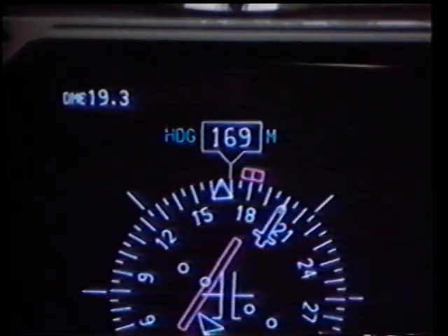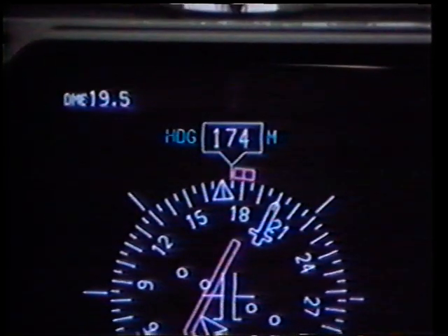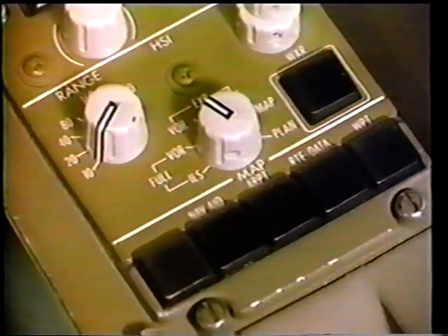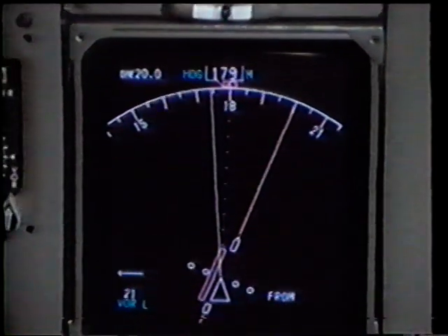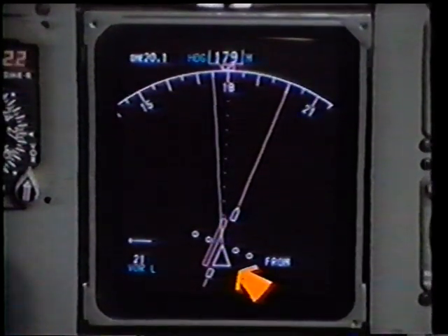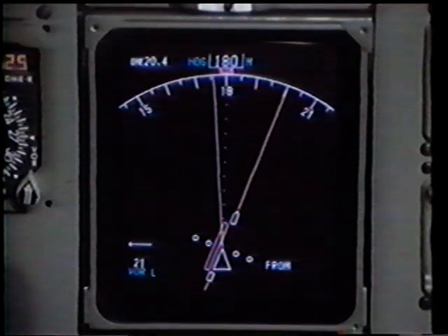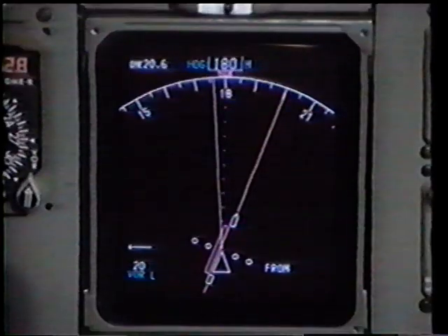By looking at the essential information in the top half of this full VOR display, the expanded VOR mode improves this presentation with a new uncluttered display. The airplane symbol, now a triangle, is at the bottom of the display. The compass rose is now shown across the top as an expanded 70-degree compass arc.